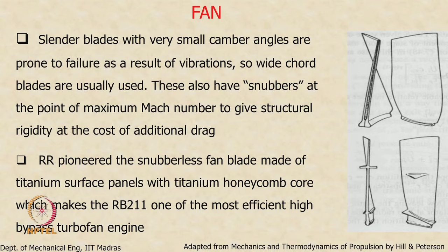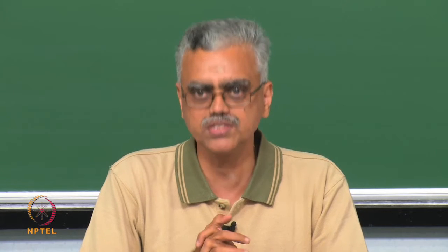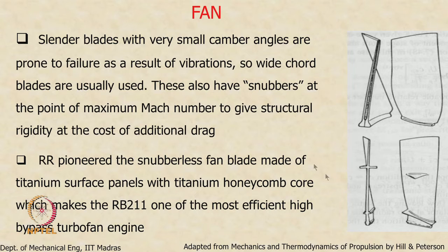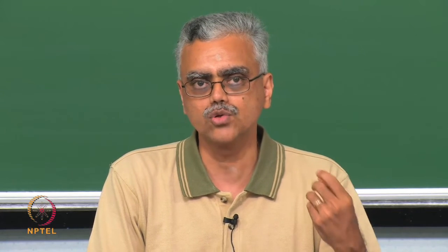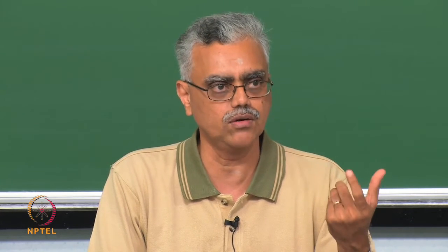Now, we looked at the gas dynamic aspects of the fan blade so far. Let us now look at structural aspects, because that is also important. Remember, many times a design may be good on paper, but it may not be possible to actually realize that in concept or in real life, and that is what we are looking at next. What are the structural issues associated with the fan? And we saw that there was a problem with the fan blade speed. So, we overcame that with the multi-spool technology.